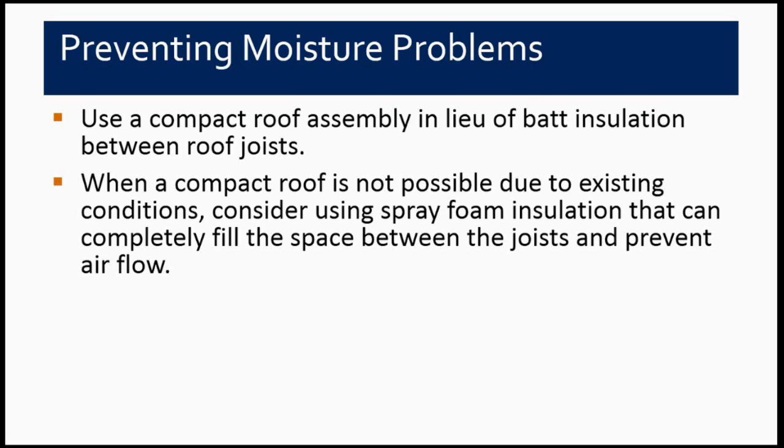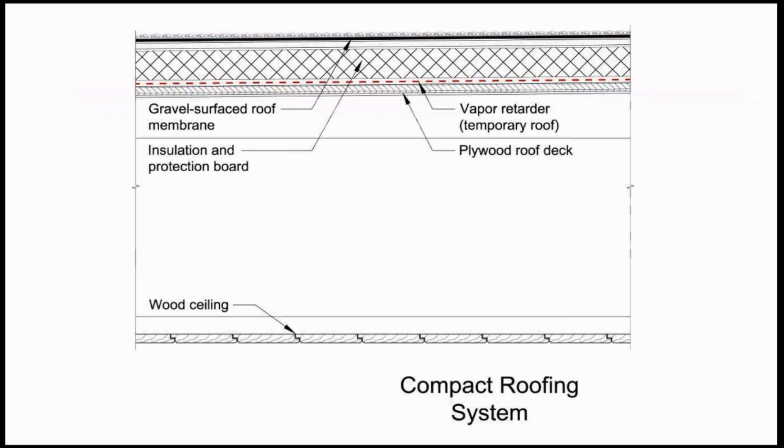We have talked about trying to pressurize it by having fans that blow cool outside air into the ceiling space above the insulation so that it redirects the airflow so that it's not coming from the interior. The problem with that is that you're going to have cold drafts and you're going to have condensation as the air leaks through those drafts.